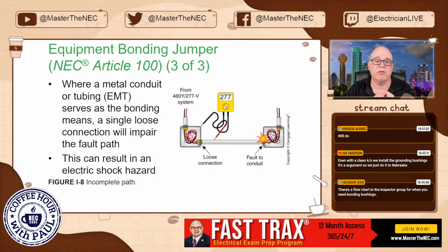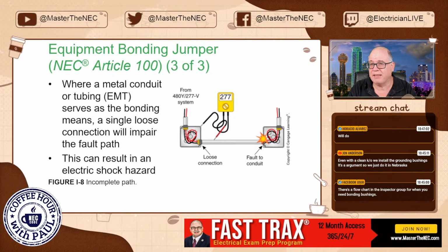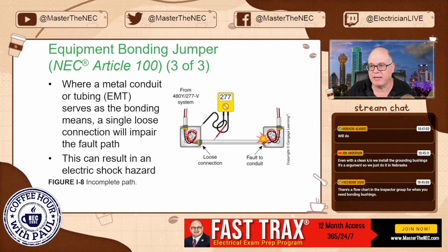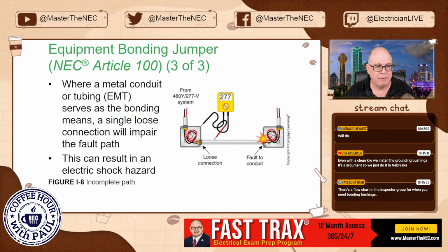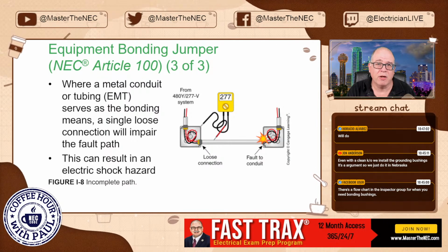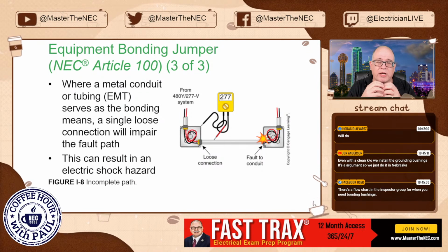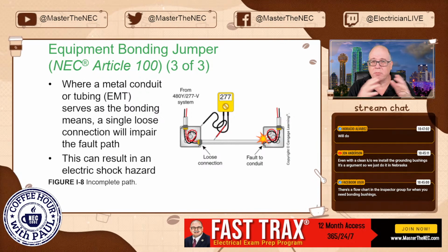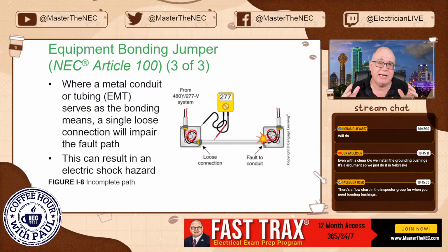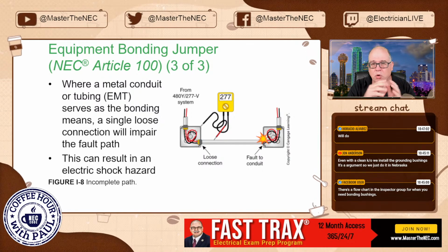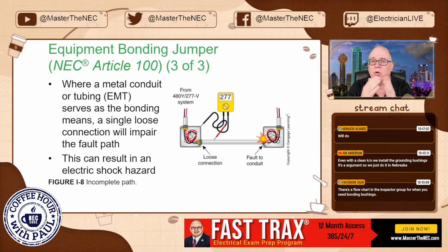What I'm saying is that a lot of engineers and designers will want you to put the wire type in there because they feel more confident that you're going to make those terminations, because that's what we're always taught. And you do have people that might get a little lax on making those lock nuts tight, or putting on a coupling properly, or the coupling could move if you don't think about expansion and contraction depending on where you install it. Maybe you're on a bridge or something and you don't follow the rules for expansion and contraction and it moves, and you could have a coupling pull loose.